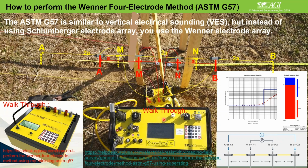To avoid that, sometimes you need one person at every electrode location. The operator will say, okay, go to the next point, then it will go to the next point over here, and then the next one. In this case it will go the opposite way. So you measure here the first one, 2A, 3A, like this, going all the way up to where you want to measure.